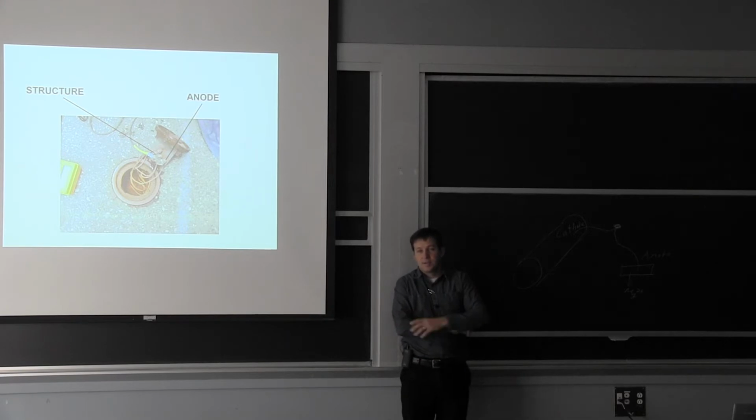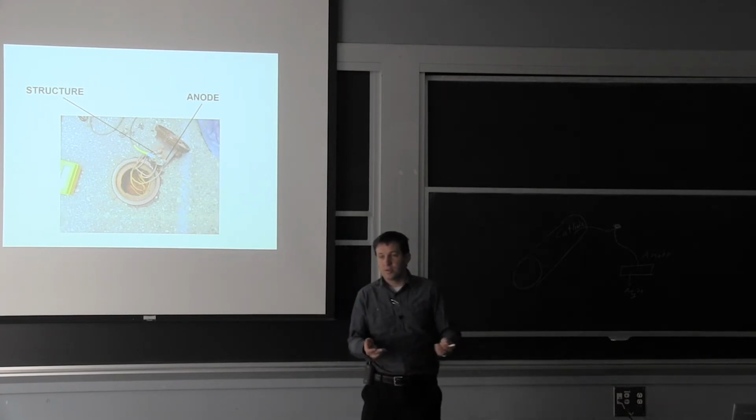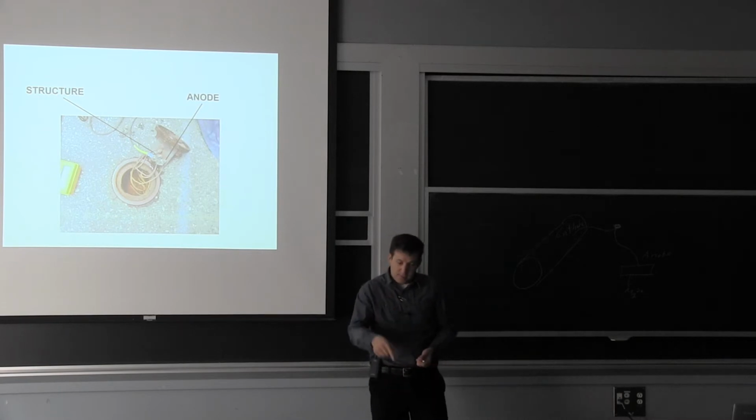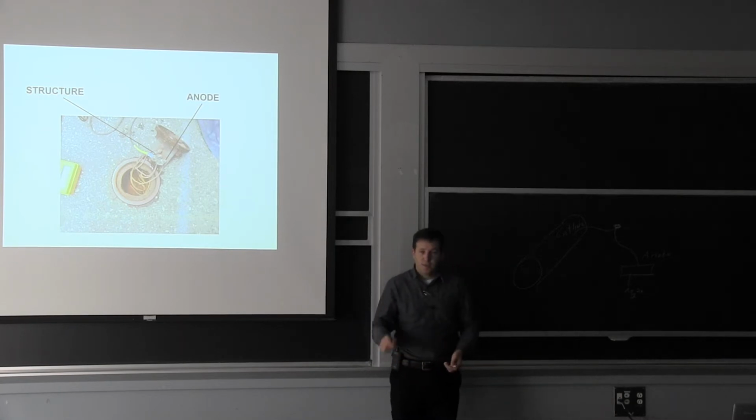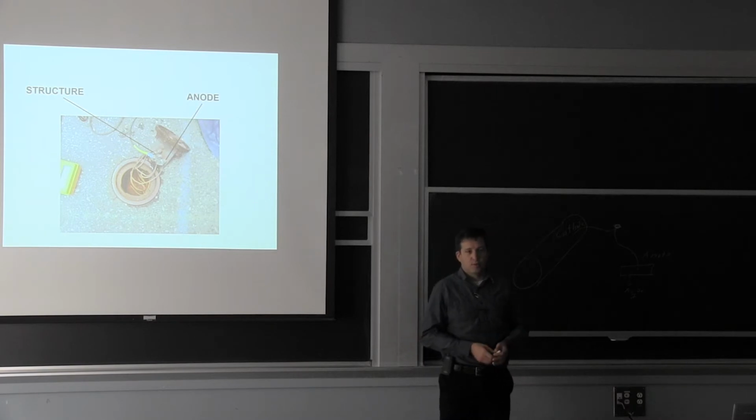So if you have a concrete slab that has reinforcing in it, and you say, oh my God, there's so much chloride that penetrated into the structure, now I want to protect it. You have to drill a bunch of holes and put these anodes closely packed and connect them back to the steel. It's a very expensive process, yet I've seen it done. If you don't want to afford replacing the whole system and you want to stop the corrosion, that's the way to do it.